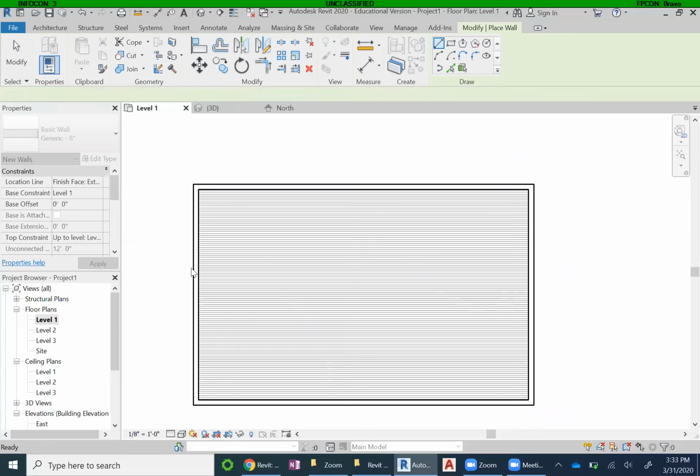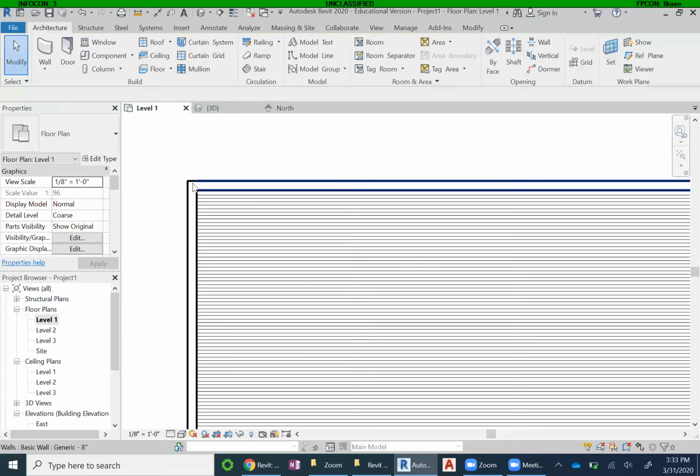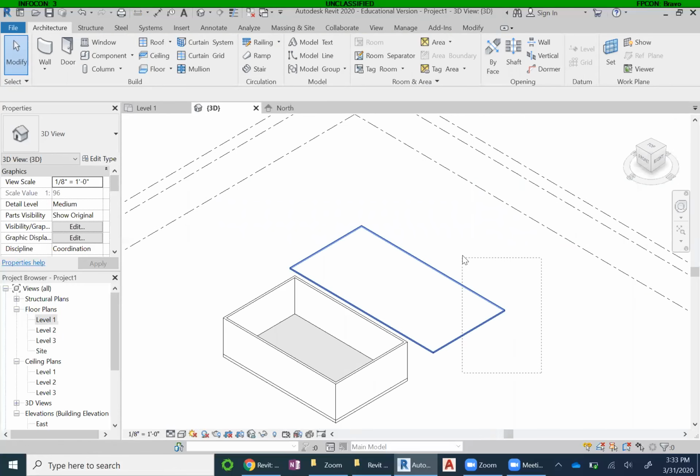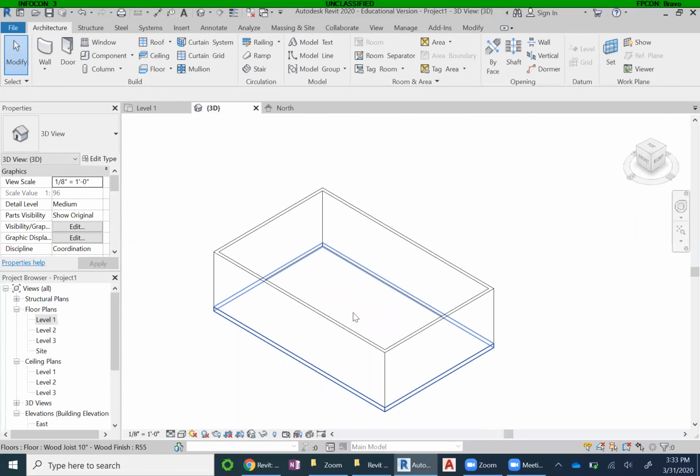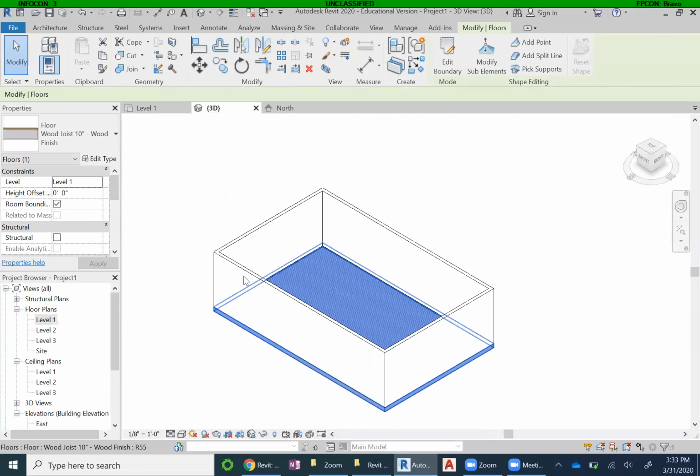And Revit is smart. Revit meshes these two things together, based on the way that the walls are built, but it meshes these together pretty slickly. So if we go back, I'm going to delete this slab real quick. If we go back out, we can see that we have our wood plank floor with our 4 walls around it. So it looks pretty slick.